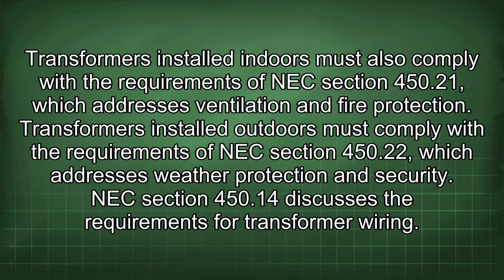Transformers installed indoors must also comply with the requirements of NEC Section 450.21, which addresses ventilation and fire protection. Transformers installed outdoors must comply with the requirements of NEC Section 450.22, which addresses weather protection and security.